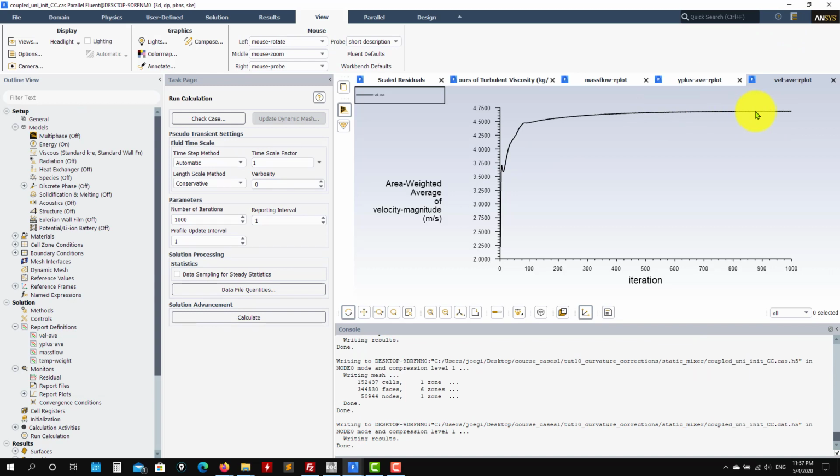In theory they should reach, I'm not going to say exactly the same solution, because you have different numerics and different treatments, but approximately they should reach very similar values. The main difference is the convergence rate, okay? And coupled solvers tend to be much faster to reach a steady behavior. However, if you have some unsteadiness, probably they are not good anymore. And this is why we don't use coupled solvers on unsteady simulations, okay? Because they're very costly, so you stay with the segregated solvers.